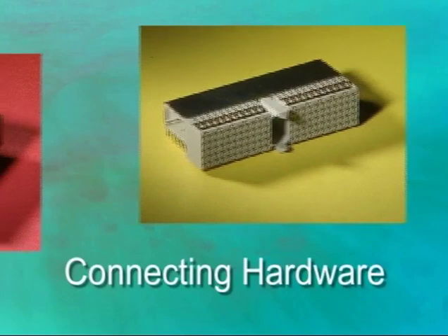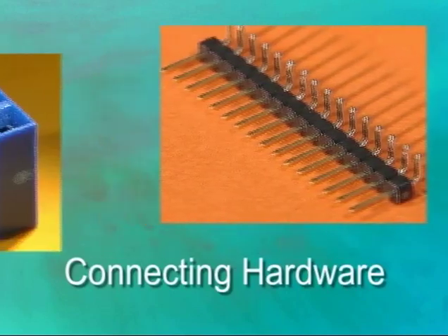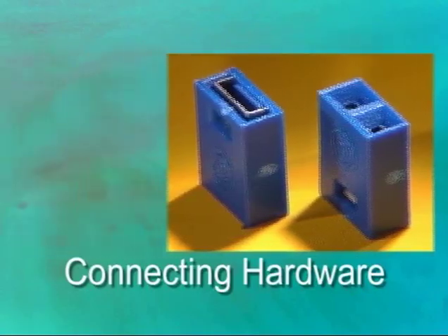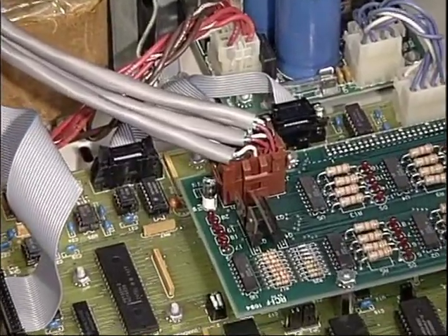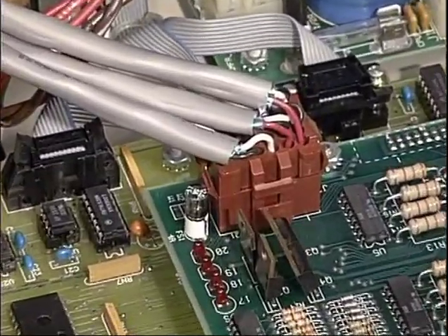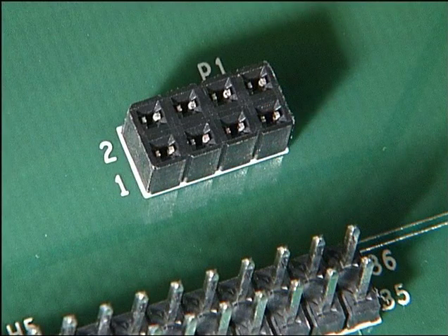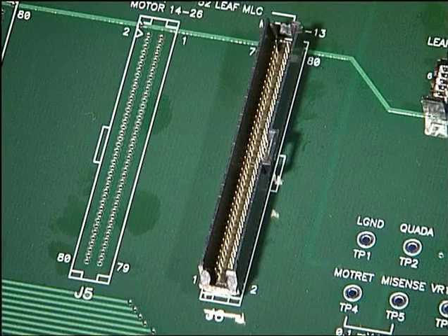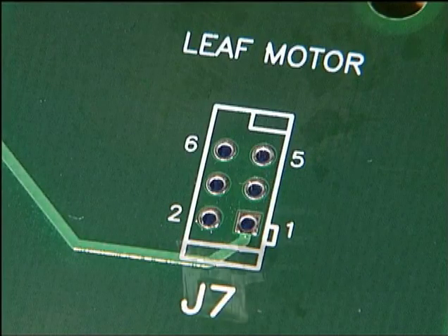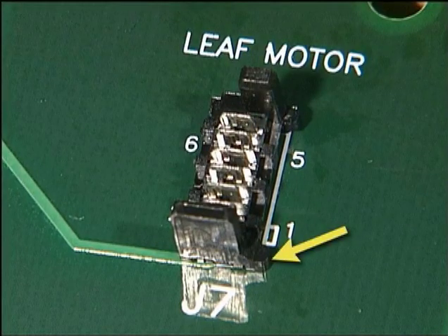Let's complete this section by discussing connecting hardware. This hardware is available in both through-hole and surface mount package styles. Connectors are attached to a circuit board so that wires, cables, and other outside connections can be made to the assembly. The reference designator for a connector is the letter P. Connectors also use the letter J as a reference designator. Connectors are oriented based upon a bevel, notch, or pin number molded into the package.